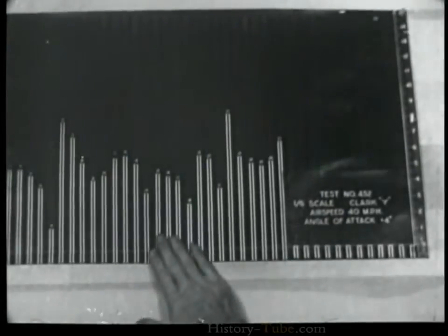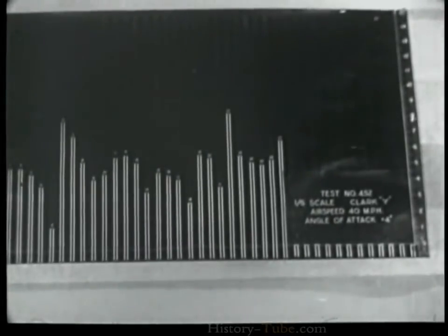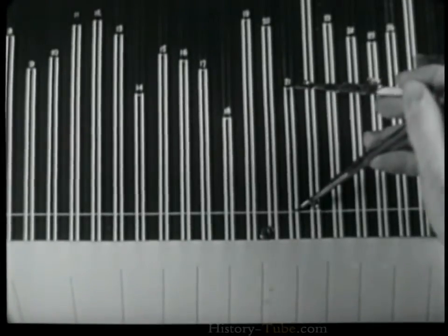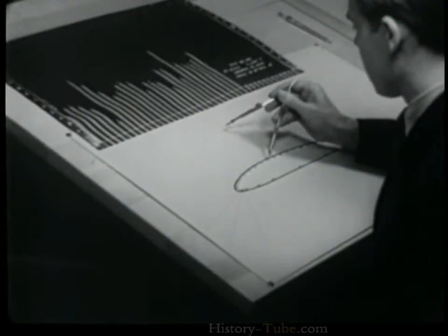Levels fluctuate slightly as minute variations in airspeed or density occur, but the ratios are constant, and the position of the liquid in the tubes shows both positive and negative values for the airfoil. The tubes are photographed to assure simultaneous readings of all tubes, and the photograph is used by engineers to plot the pressure curve.